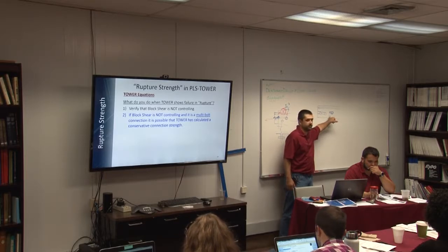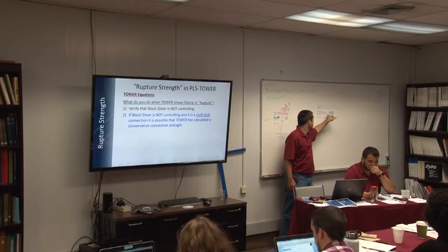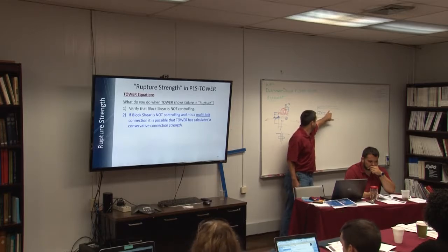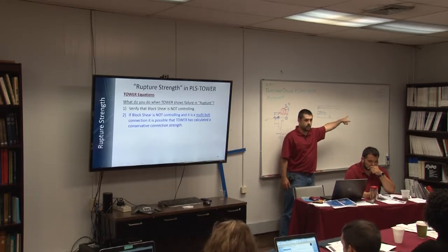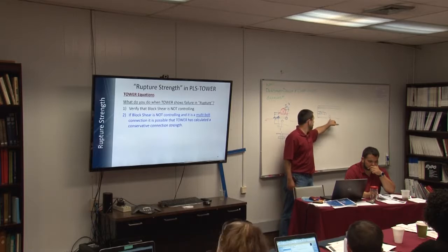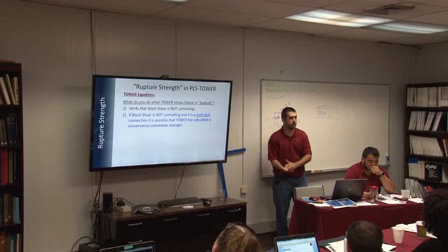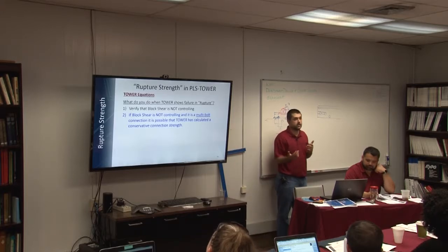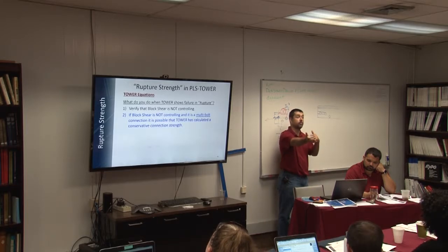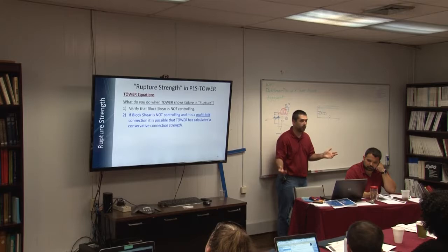So if this is limited to 5 kips and we have 3 bolts in our connection, then if I have 15 kips of demand, I have 5 kips in each bolt, and then if this has 5 kips, it's going to crack. That's the assumption they're making, right? And all I'm saying is that I can't argue with that as being wrong. I think that is a simplified assumption that's consistent with what we do when we calculate bolt shear. We say, what's the total demand divided by the number of bolts? That's the bolt shear that we have.